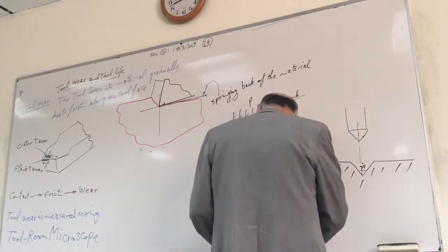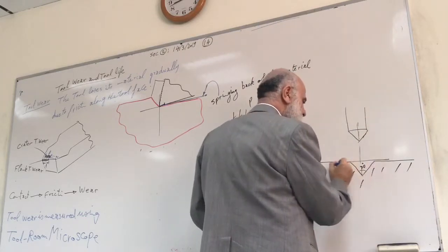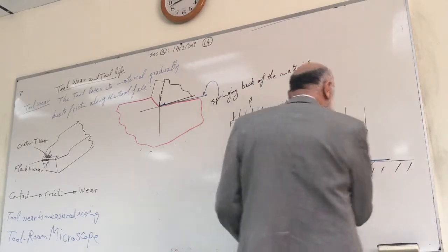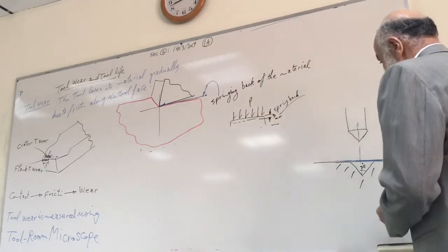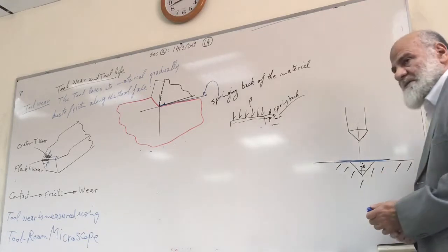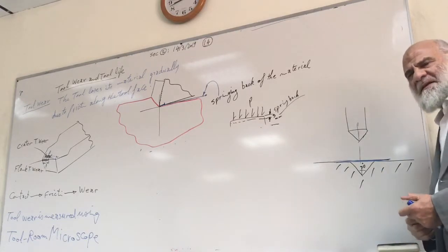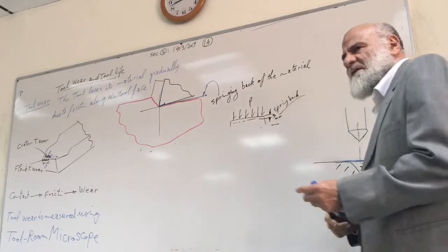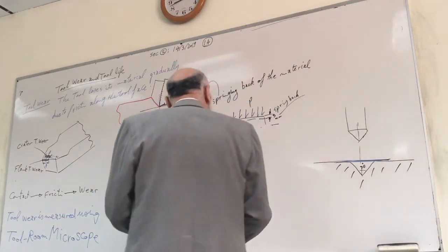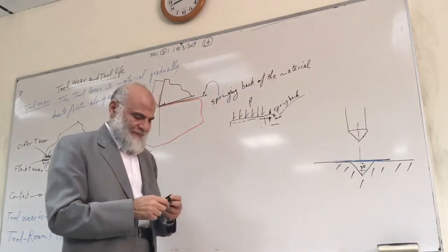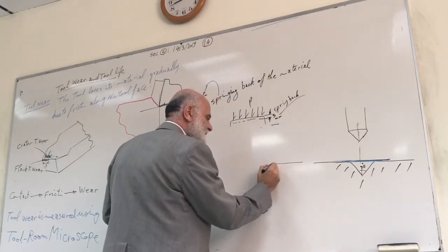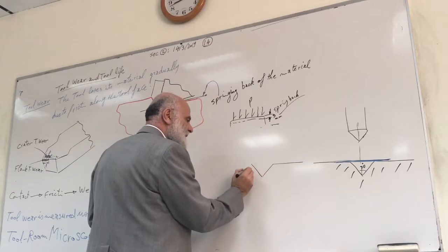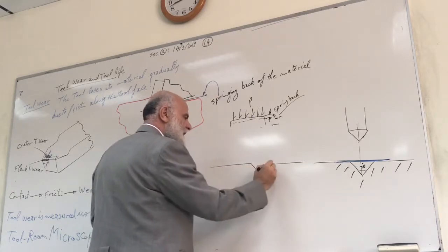Then I will put a sheet on the top surface of the die. I will put a steel sheet, the punch comes down, pressing the sheet inside. It is like deep drawing, but it's called bending, to form the angle. Then it will be like this. This is the die and the punch, both together.